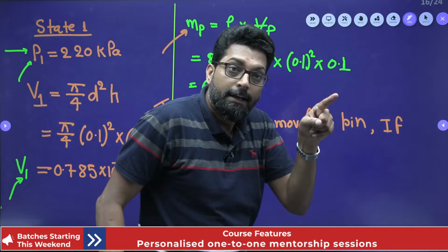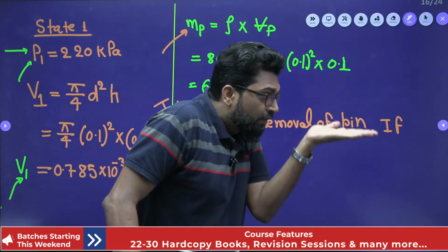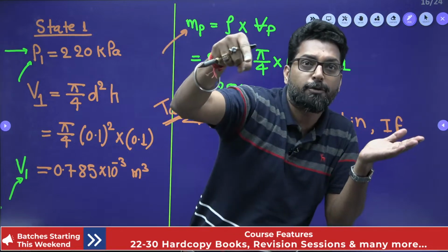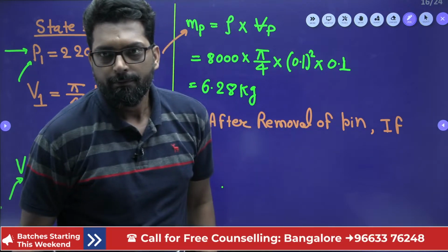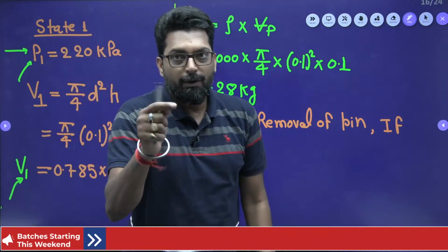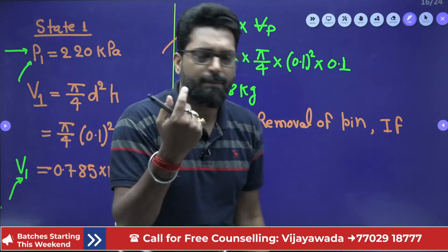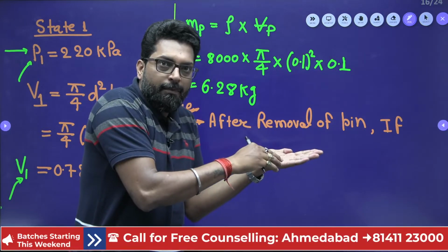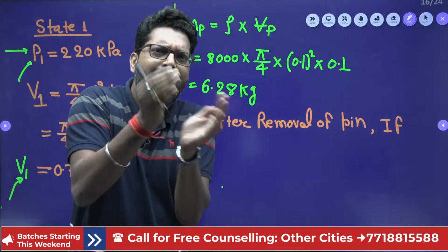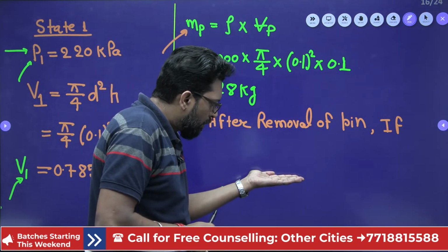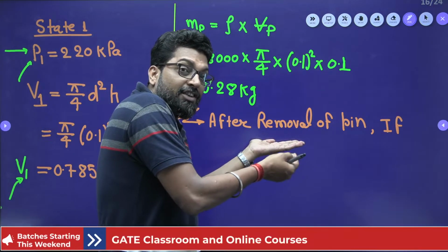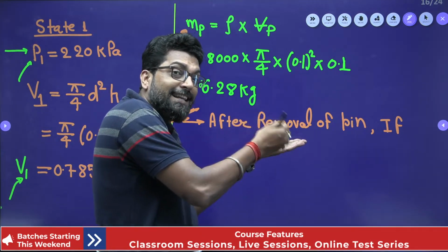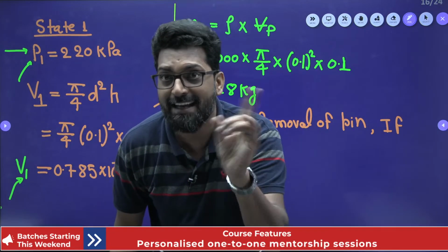But while the piston touches the stop, you assume it touches the stop, and while it is touching, the inside pressure is still high compared to the atmosphere. Then it must touch the stop. At which condition can it not touch the stop? If the inside pressure is equal or less than atmospheric, then it does not mean the piston will touch the stop.